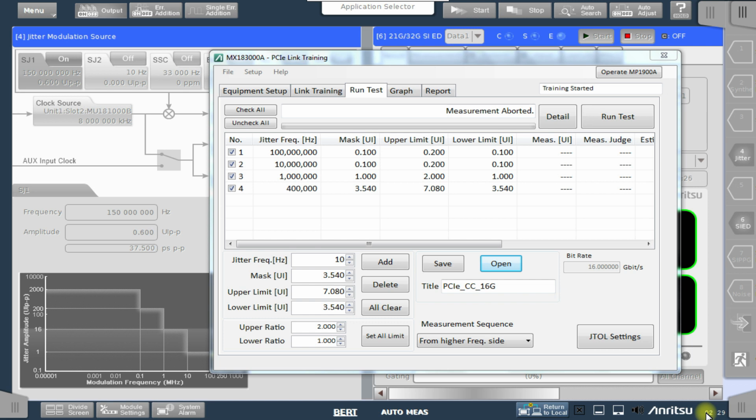This is to ensure that the DUT receiver can handle highly jittered signals and doesn't get distorted by other system components, like, for example, power supplies. During the test, jitter generation sweeps through the specified amplitude ranges with a given granularity for all specified jitter frequencies as displayed in the table.